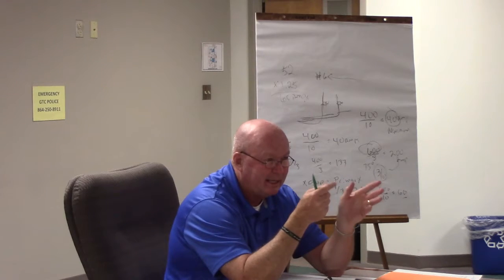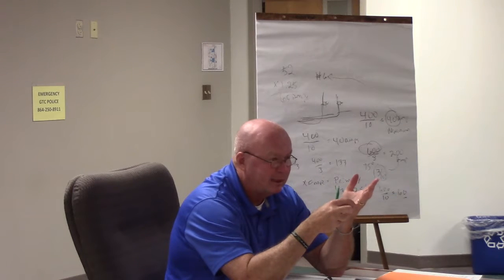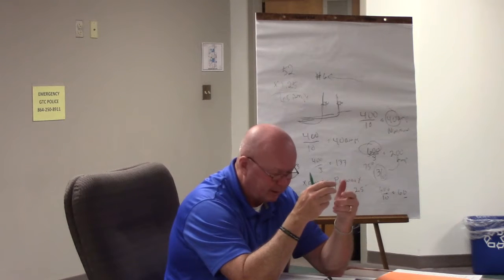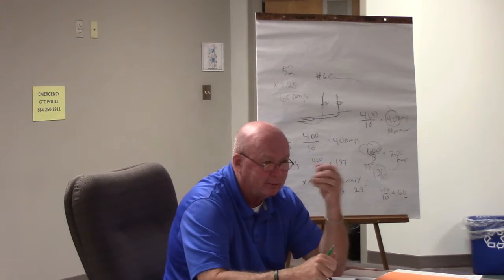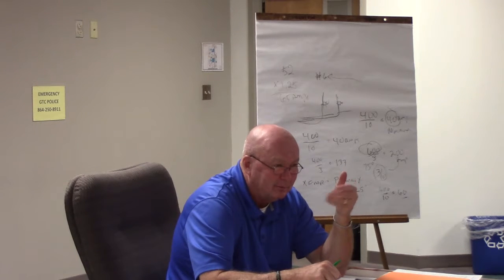3,000 VA is not much. Matter of fact, 3,000 VA is only a couple of small appliance loads, because each small appliance load is 1,500. So anything over that, we start to really deduct, because in a house, what's going to happen? You're going to turn everything on at once? No. Your kids might, but you're not.